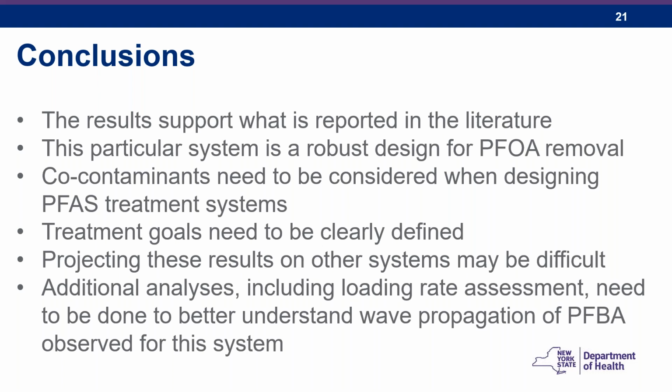Another thing that we were interested in seeing with this system, a GWUDI system that has a pretty extensive pre-treatment, is that you'd have to look at these results relative to that. So in a sense, you could almost say that the performance of this GAC contactor would be a best case scenario. Maybe best case scenario is overstating it, but look at this performance relative to what you could anticipate from a surface water system that may have a much higher organic loading. Even after some pre-treatment, the organic loading onto the contactors will be higher than what we're seeing in this system. So that's something else that would have to be considered.